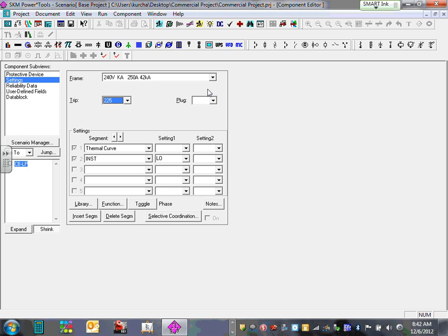Darren, if you're overwhelmed with circuit breakers, you will be, because you're going to be dealing with different manufacturers, guys. For the time being, take what Chad tells you. When you start doing the calculation, you're going to contact the Square D rep and ask which circuit type is best for this type of panel, which is a 100 amp panel. They'll be more than happy to tell you it's a KA or a QP. You know what I mean?